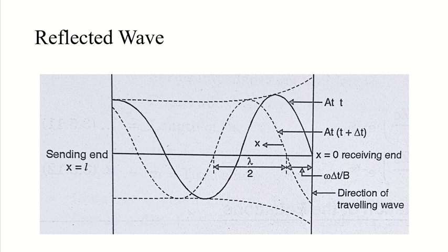So the current density on the outer portion of my conductor will be higher, and the current density in the center of my conductor will be close to nil or almost zero. And that is for AC current only. And when such a thing happens, we call it skin effect.